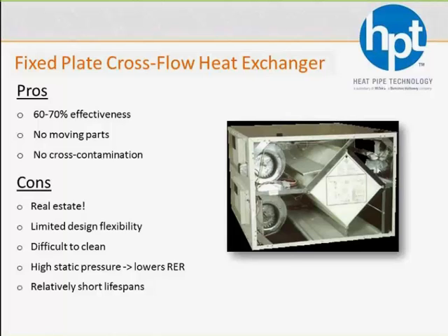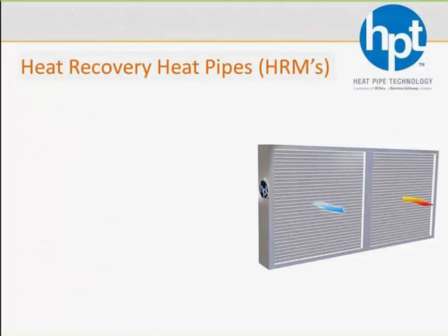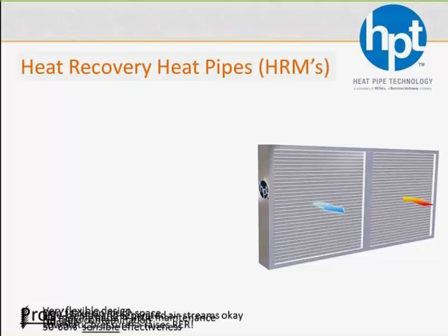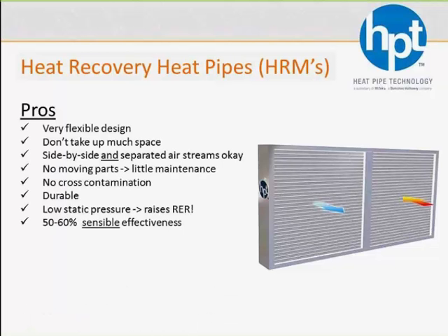And of course, and I spoiled this earlier, so I apologize, there is this thing called a heat pipe that will hit this 50% mark. Upsides to it: no cross-contamination, a lot more durable, going to last quite a bit longer, sometimes up to 30 years, even more, depending on the kind of conditions it's in. They certainly don't take up a whole lot of space. They're going to look just like a coil. And we're generally going to be above 50% effective when it comes to energy recovery.